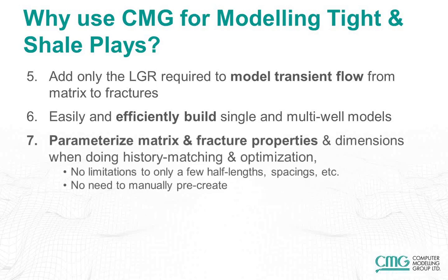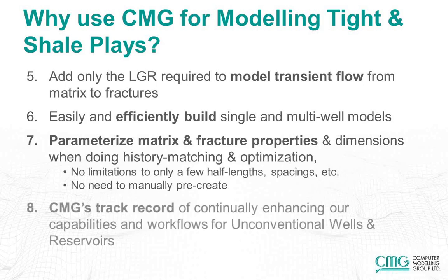And we have the ability to parameterize matrix and fracture properties and dimensions when doing automated history matching and optimization. So with this, we can look at the entire search domain instead of being limited to a few half-lengths or spacings. There's also no need to manually pre-create these cases, as CMOST can automatically generate these cases for you. CMG also has a track record of continually enhancing our capabilities and workflows for unconventional wells and reservoirs.